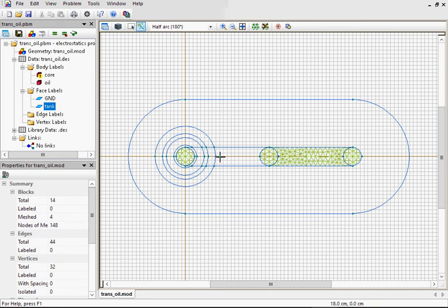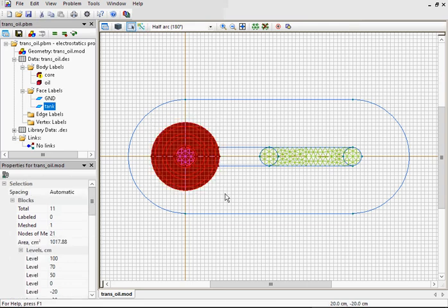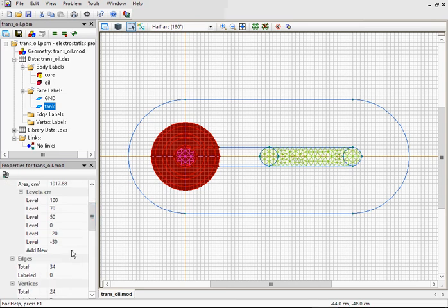And again the insulation layer. Now let's switch to select objects mode and assign heights. I select the winding and assign levels 42 centimeters and 48 centimeters.